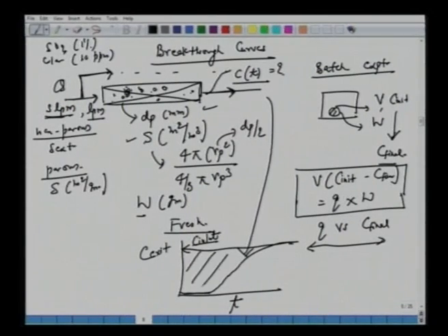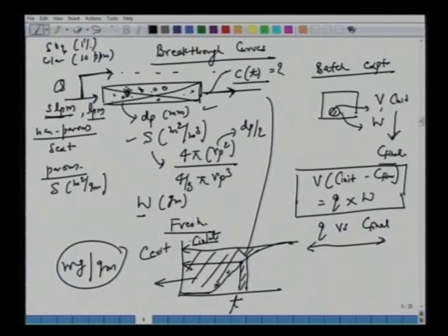One can calculate from experiments. So these are the data. One can calculate the area under the curve. From here we can find out how much is the loading, how much amount has been adsorbed, by material balance. This we also did in the earlier class. Take this response at a time of del T, see how much is C exit, and make a material balance: Q is constant, C inlet minus C exit, which is a function of time, times del T. If you integrate from 0 to infinite time, we can find out how much amount has been adsorbed.